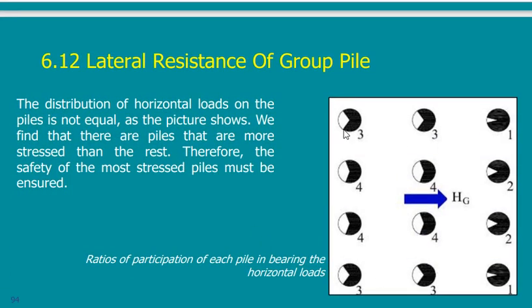Lateral resistance of pile groups. This is something related to the lateral resistance of the piles. Do you consider, if you have a group like this, and I have a lateral load in this direction, will all piles carry the same lateral load? There will be a difference. What is this difference? The piles in the front will carry the whole amount.